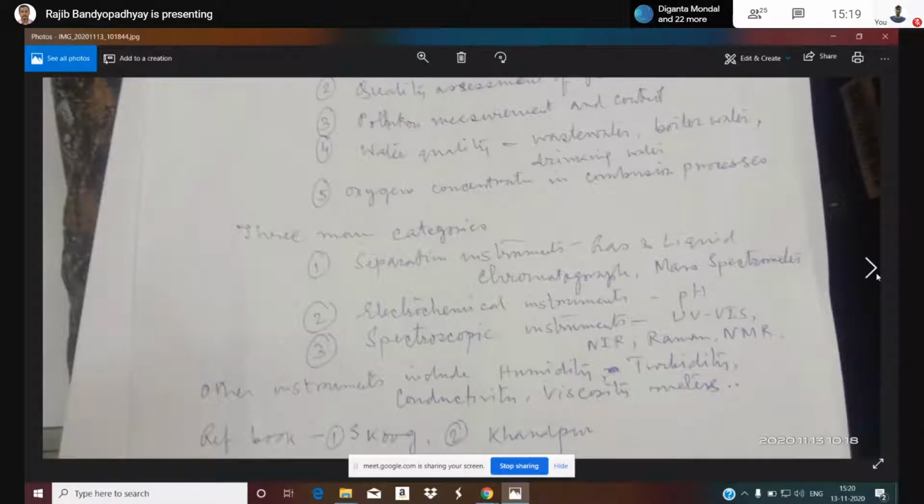So it is used for drinking water, and this is also true for the water going to the boiler, because if we allow water with many elements and compounds in it into the boiler, there will be corrosion and coating inside it, and we would have to replace the boiler tubes quickly. So we have to ensure that.